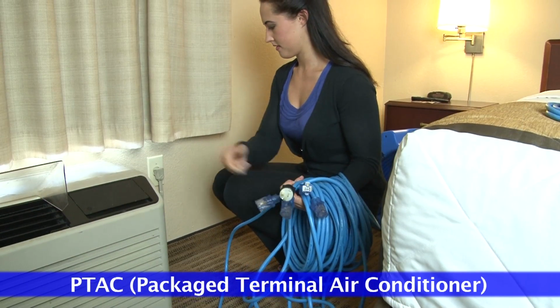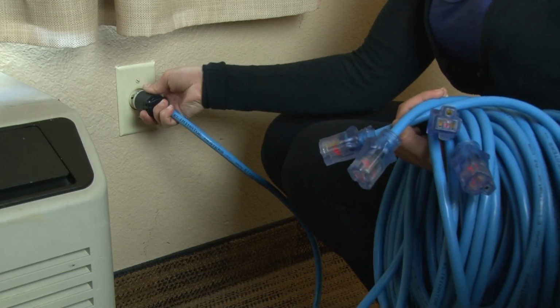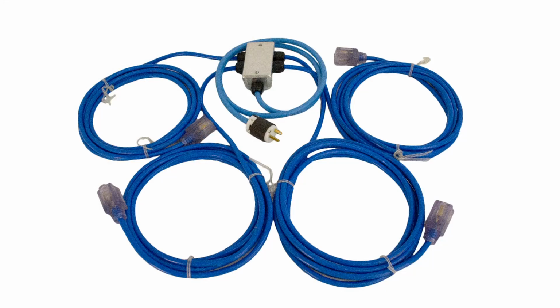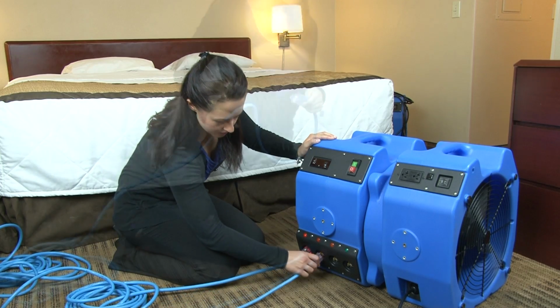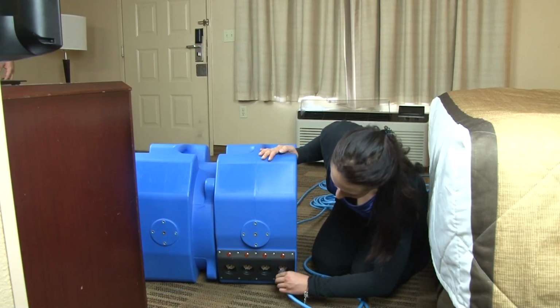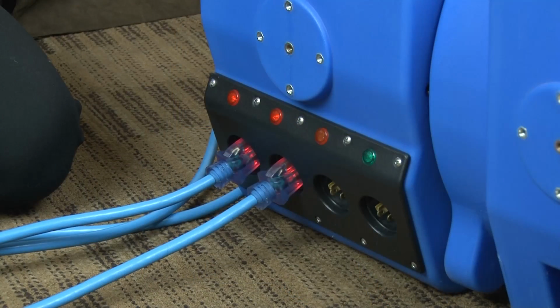If your hotel room has a 20 amp PTAC, unplug the PTAC and plug in the Convectex AC splitter. The splitter provides you with 4 8 amp power cords. Plug the splitter's 4 power cords into 4 of the heater's available receptacles. Be sure not to use the receptacle under the green light. This receptacle should be connected to a dedicated circuit outlet.